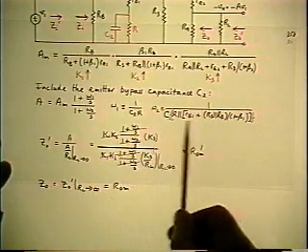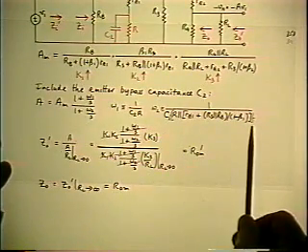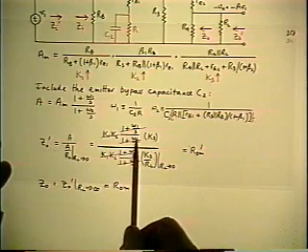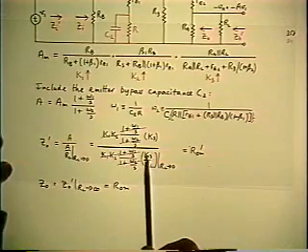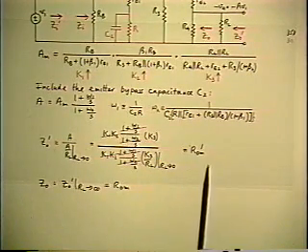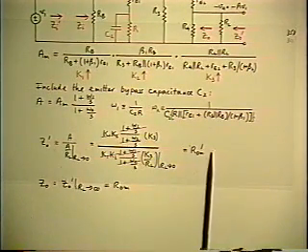And the same thing with the omega 2. That doesn't have RL in it, so that cancels, or I should say its entire factor cancels. So in this particular case, the corner frequencies disappear and they don't affect the output impedance.